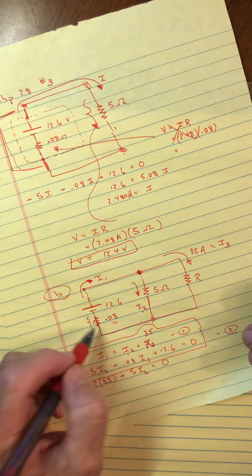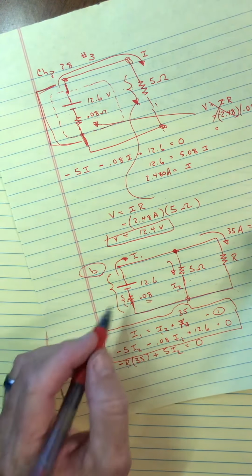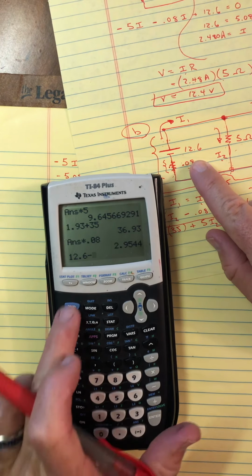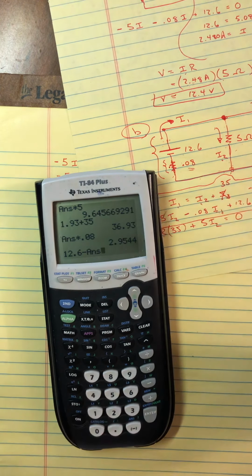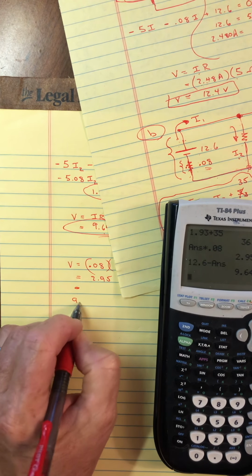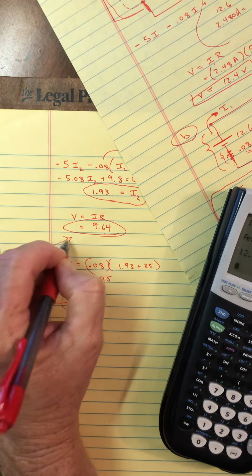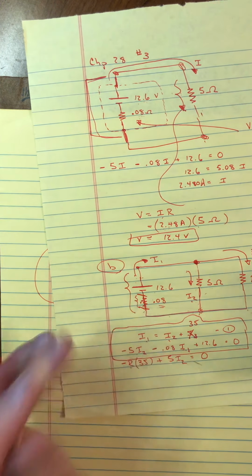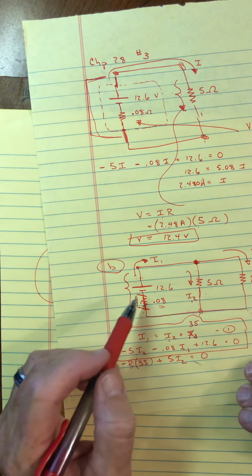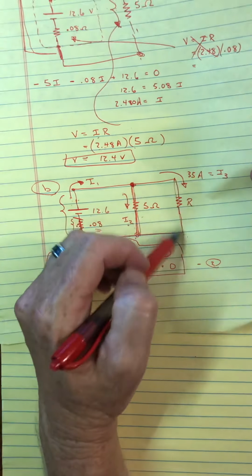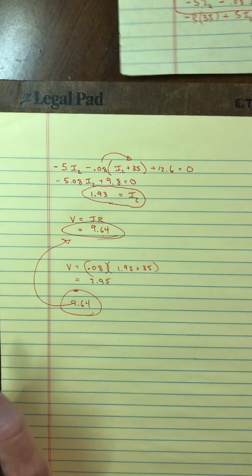So that's how much we lose. That's why if we, again, take our voltmeter over the terminals, we would not get the 12.6, but the 12.6 minus the voltage loss trying to get the current out of the battery. And of course that is less than the 9.64 that we got up here. And so again, maybe it's easier to see when we see it as a drop in the internal resistor taking it away from the EMF, so the terminal voltage is less. That's the voltage on the headlights, and for that matter, the voltage on the starter motor. All right, hope that helps.